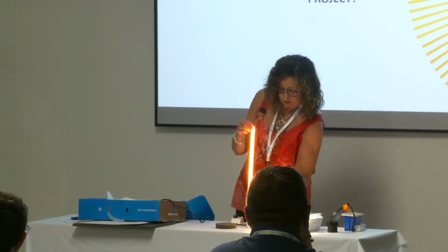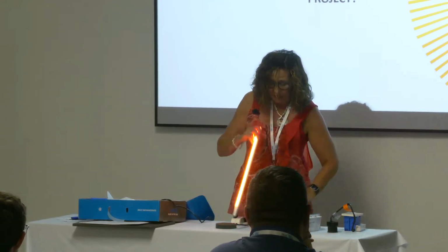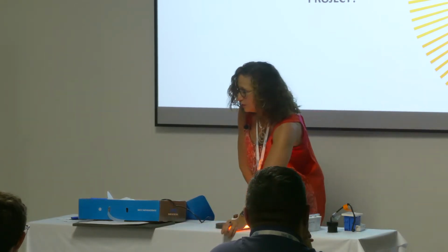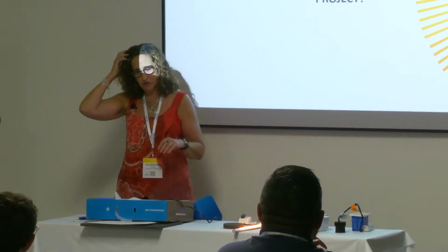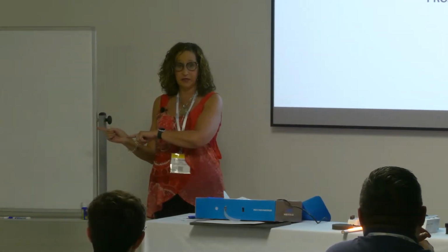And the reason is, there are many reasons, but the main reason has to do with the color rendering and the spectral power distribution of the various sources. And for that, you should come and hear Tony Esposito speak next, because he's a genius and he invented the way to measure it, and it's amazing. That being said, you cannot get two sources from two different manufacturers that have a pre-programmed dimming curve like this, right? What's the highest and what's the lowest, they will never match.